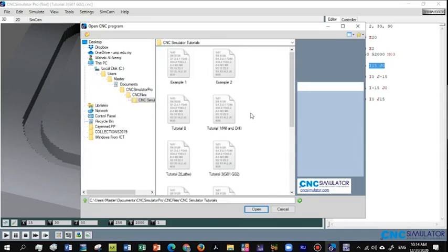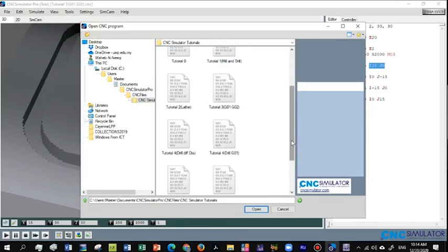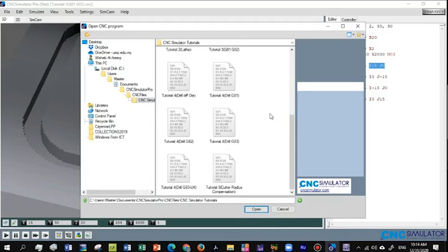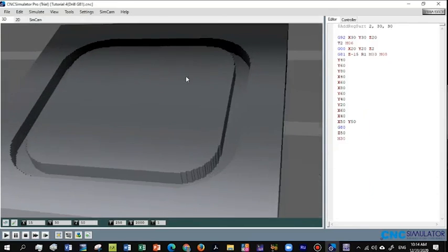Another example here is for the drilling. We already have the drilling, and we said for the drilling, we have different canned cycles. We can use G81, we can use G82 and G83, depending on the requirement, the parameters that we are going to use to make the drill operation, and also the requirement for the size of the drill, the length of the drill, and so on.